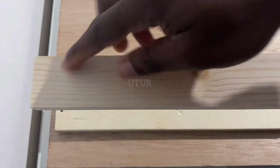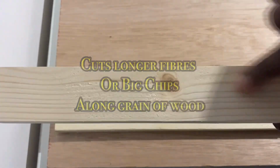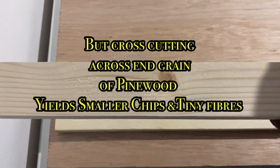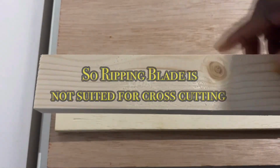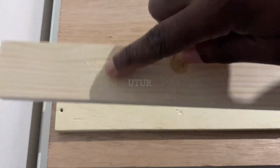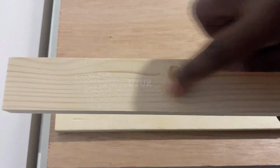The ripping blades typically have about 24 teeth. They have large gullets between each tooth to move out big chunks of wood. So it essentially cuts long fibres of wood or moves out big volumes of wood when cutting. So essentially, you need big gullets for ripping, to rip in the same direction as the grain to enable big chips to come off the wood.